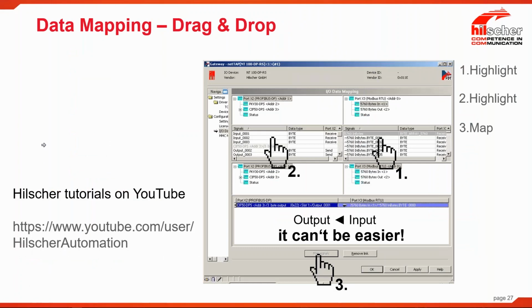And as I mentioned before, the process is literally 3 steps. Choose the protocol and whether it's a master or slave on one side, choose the protocol and whether it's a master or slave on the other. And then the third step being the I/O mapping.